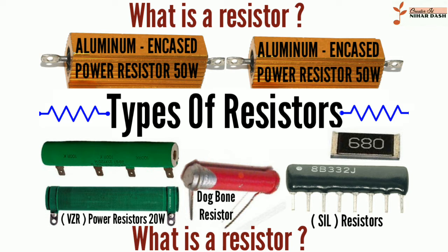High-power resistors that can dissipate many watts of electrical power as heat may be used as part of motor controls, in power distribution systems, or as test loads for generators. Fixed resistors have resistances that only change slightly with temperature, time, or operating voltage. Variable resistors can be used to adjust circuit elements, such as a volume controller or lamp dimmer, or as sensing devices for heat, light, humidity, force, or chemical activity.